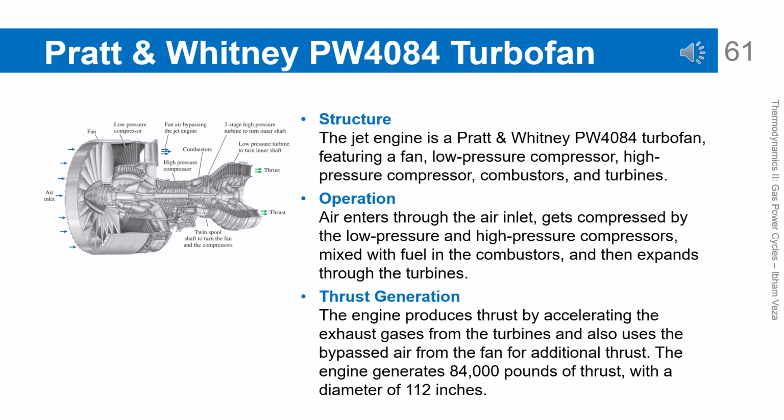Air is compressed in several stages before being mixed with fuel and burned. The hot gases then expand through multiple turbine stages. In addition to thrust from the exhaust gases, most of the thrust comes from the fan bypass flow. This shows how modern turbofans emphasize propulsive efficiency.